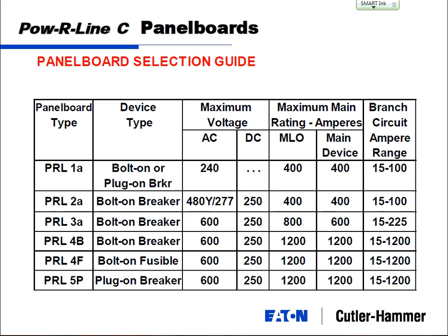That's the thermal part of the thermomagnetic. The magnetic part is what looks at short circuits. The magnetic part of the circuit breaker is looking at current that, say, is in the 200 amp range on a 20 amp breaker, so 10 times. That current is going to create a magnetic field. The more current, the more magnetic field, and it's going to push that trip bar as well. The magnetic field is going to do something on the inside of the circuit breaker to hit that trip bar.